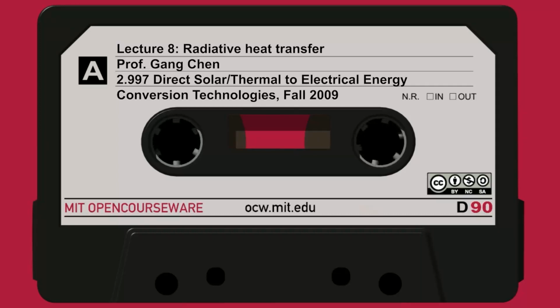And so that means the thermal efficiency, right? What comes in from the solar is sigma Ts^4 power, and the amount of heat transfer that actually happens is sigma Ts^4 minus sigma T^4. And the thermal efficiency is 1 minus the ratio of temperature to the fourth power. So the higher the temperature of the absorber, the lower the thermal efficiency.